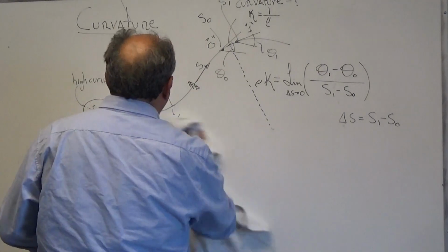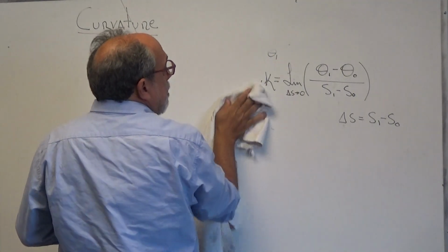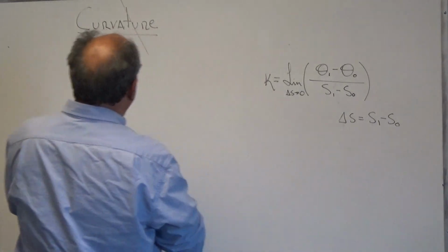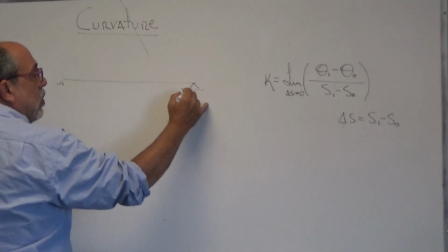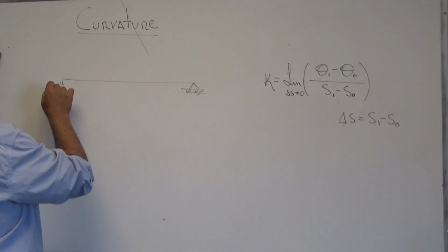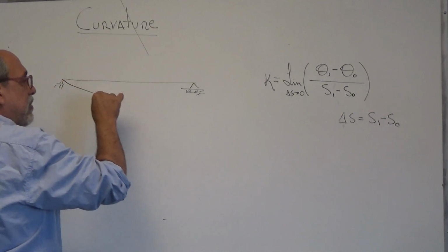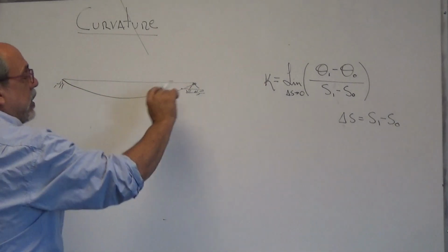What I want to say is that our lines in structural engineering are usually very shallow, right? Because we don't allow things to deform very much. We like things to stay kind of where they were before they were loaded. So when we draw the deflection of a beam, it's really exaggerated, right? The beams are not really deflected like that. We can hardly see them.